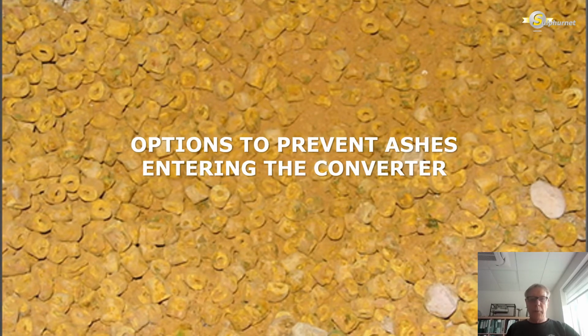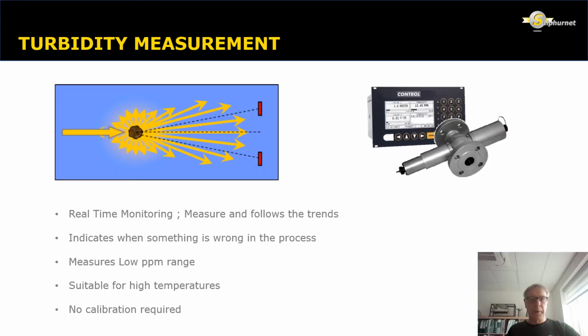If you look at the options Sulphurnet can offer to reduce these costs, we have two possibilities. The first possibility is the installation of a turbidity measurement system. That is a real-time online monitor system giving you direct information about the ash level in the sulfur. So you don't have to go to the lab, do the analysis and come back 2 or 3 hours later with the results. It is a real-time monitoring.